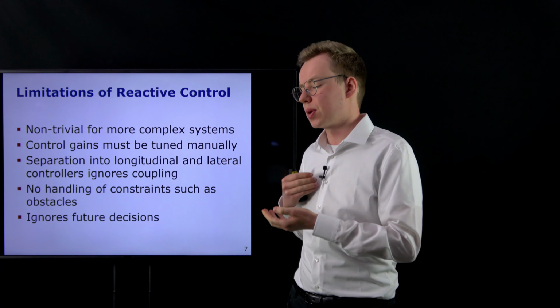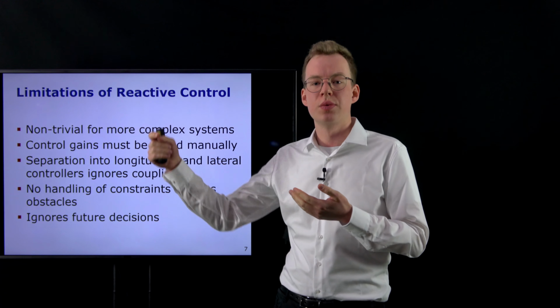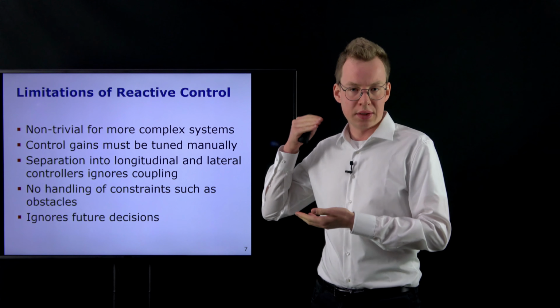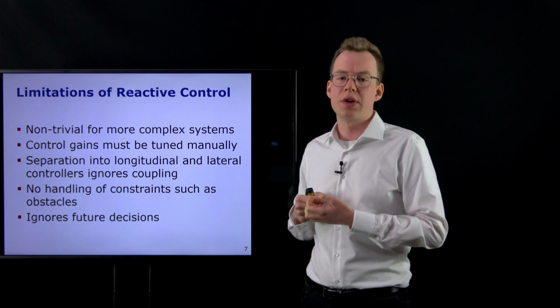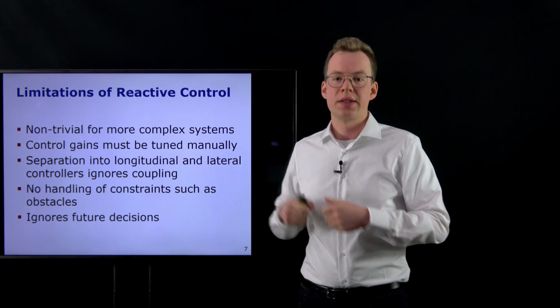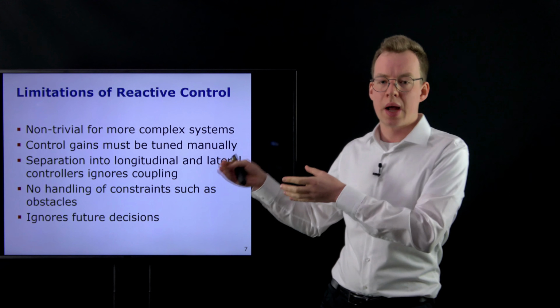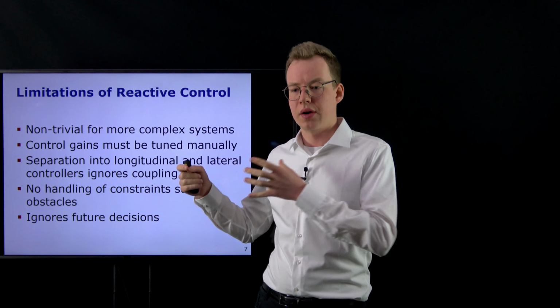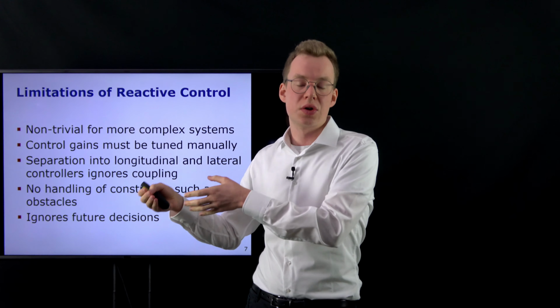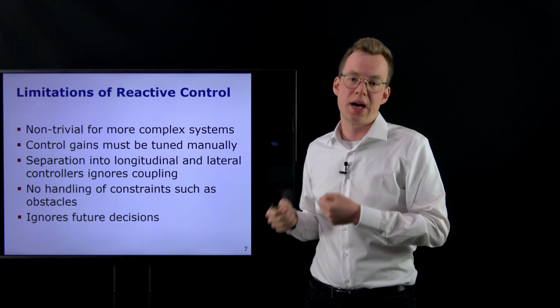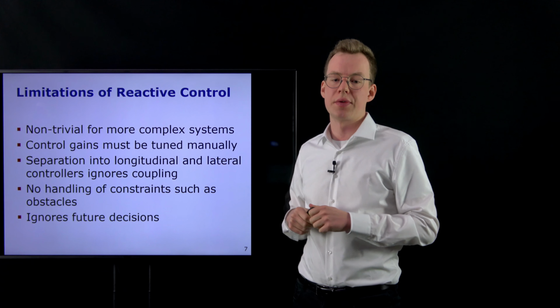So imagine that you're controlling a car and you want to safely steer around a corner. In that setting, you would want to reduce the velocity in order to make steering around the corner simpler. But here, when you decouple this, the PID controller doesn't know about the fact that the Stanley controller has a hard time making its turn around the corner.